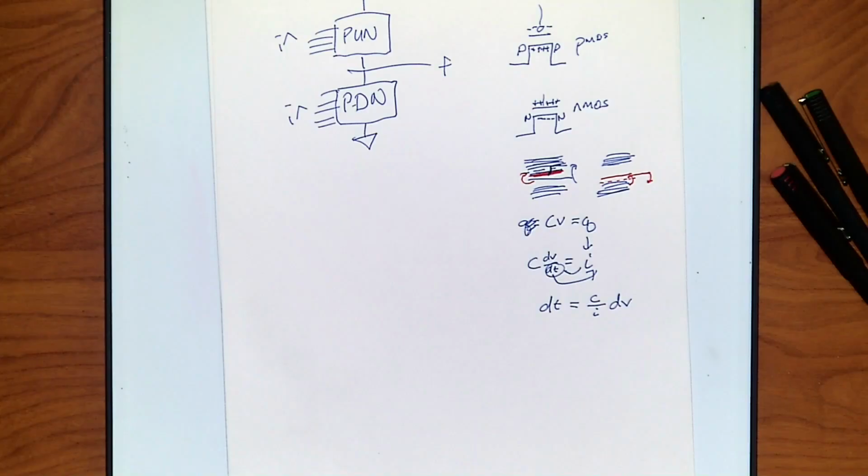That was an ultimate solution because with BJTs, since you can just slam current into those things, you can make those stupid fast by nature. And with enough current flow, even though I lose some voltage, I don't really care because I got a lot of oomph. The disadvantage is I got a lot of oomph, right? It takes a lot of power, which means I generate a lot of heat.